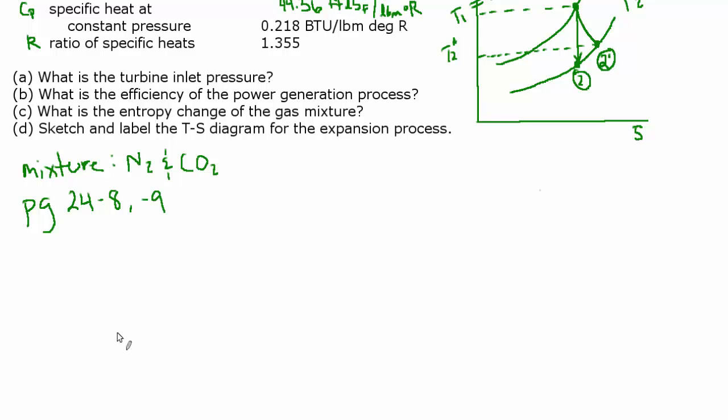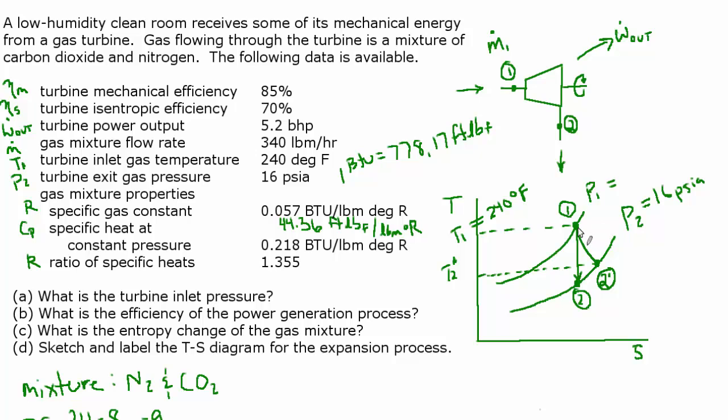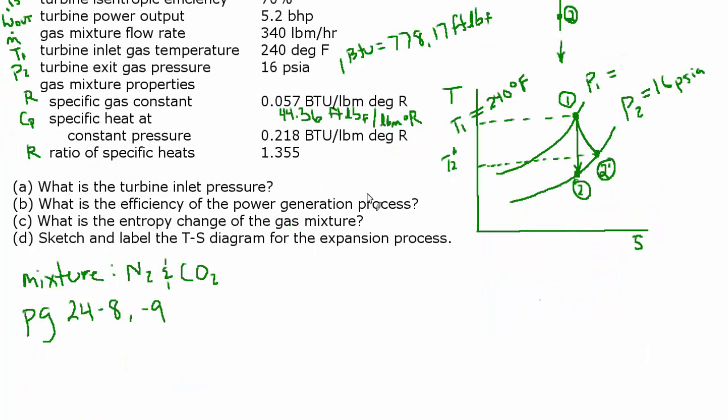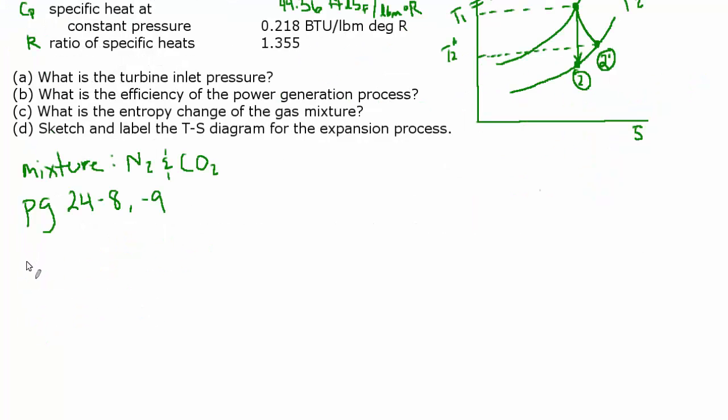In our case, we want P1 for an expansion process, and we can list some of the assumptions for that process. We know it's not isentropic, but we might be able to account for the fact that it isn't. So I'm going to put that one there. Adiabatic, meaning there's not a significant amount of heat transfer happening during the expansion. That's not to say the temperature isn't changing, but the Q, the amount of heat going in and out of the system, is approximately 0.